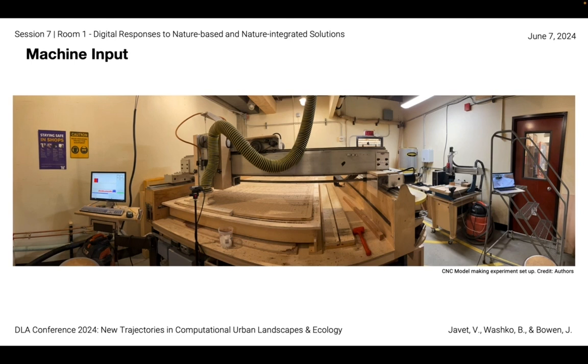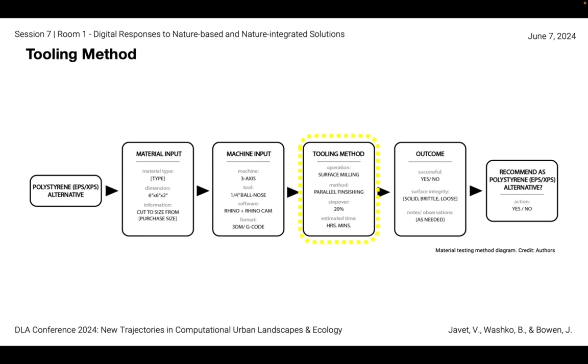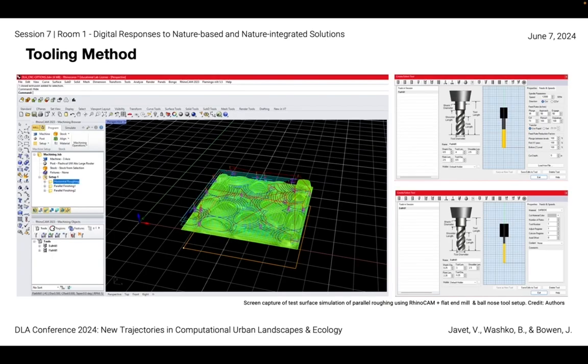With these untested materials, the decision was made to assume a comparable density for material-based feeds and speed calculations to that of MDF. Unlike polystyrene, most materials have a density and hardness that requires multiple passes of machining to achieve the desired product. The CNC-enabled router used in this experiment has a maximum spindle speed of 12,000 RPM. With this limiting factor, the final cut speed of the testing operations was set to 73 inches per minute and a plunge rate of 35 inches per minute.